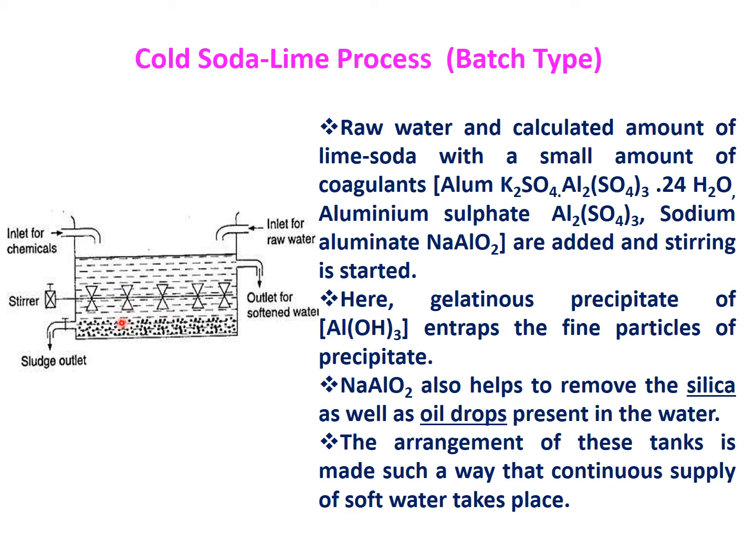When some aluminum salts are present in hard water, they react and form the corresponding aluminum hydroxide. That aluminum hydroxide is a gelatinous precipitate, and during settling down it will trap the small precipitates formed by other hardness causing salts and settle down at the bottom.